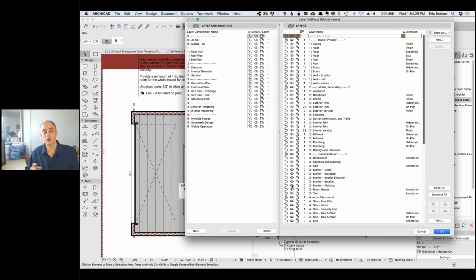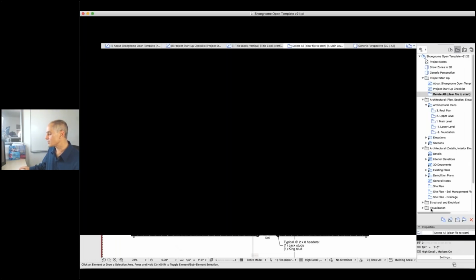Because there are markers, remember, that define elevations and maybe some defining sections that are already pre-placed onto sheets. While you'll always need to move them around depending on your project size and complexity, having them pre-placed on the sheets is a time saver. So in general, you don't want to delete the markers accidentally. You want to leave them, move them into the right position, etc.